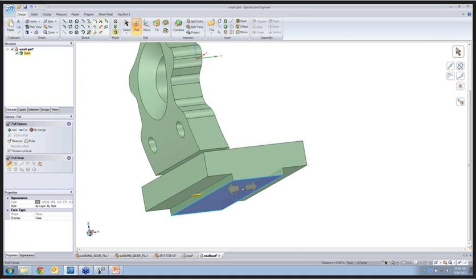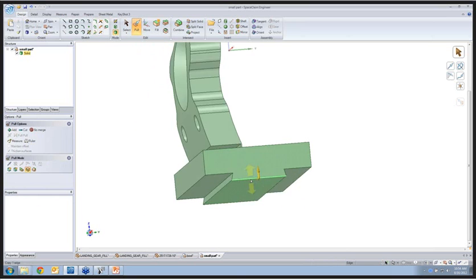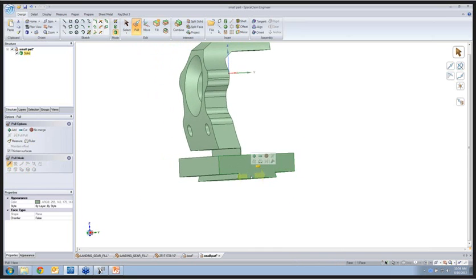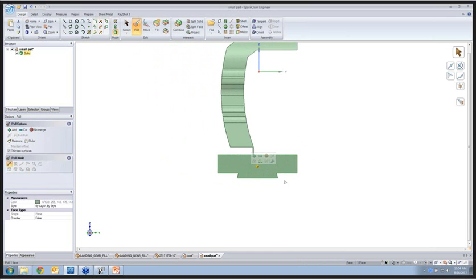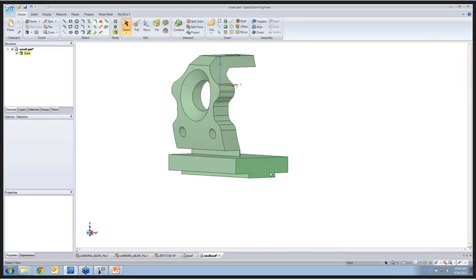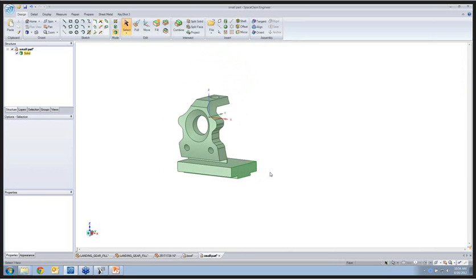Well, anytime you need to modify geometry, you generally want to use that pull tool. The draft capabilities are all built right within. So just based on the way that you select things, the software knows what you're trying to do, and it automatically puts that draft on those faces. And you can see it. I think a typical dovetail is 14 degrees, but you can always change the angle depending on what you're after. So that's one part.